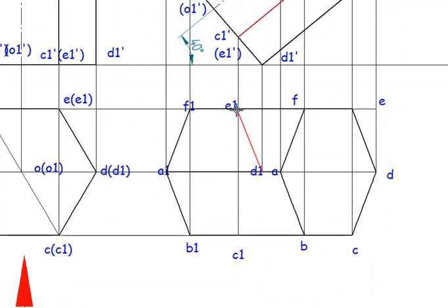We are going to join till this point E1 dash. So from here, C1 point, E1, from here till this point is going to be a dashed line. Now you can see that the line joining D1, everything is in hidden lines. So we are going to keep this inside the bracket.